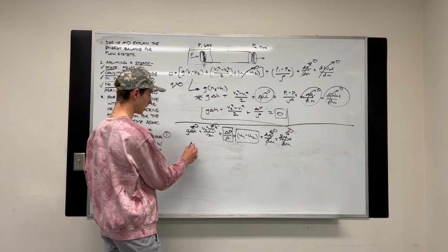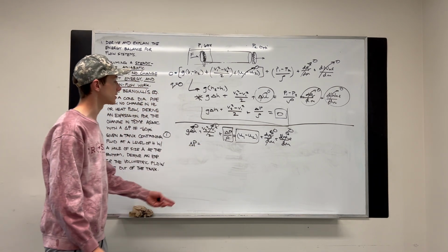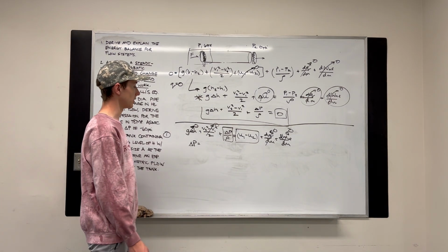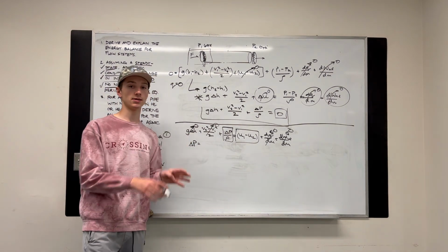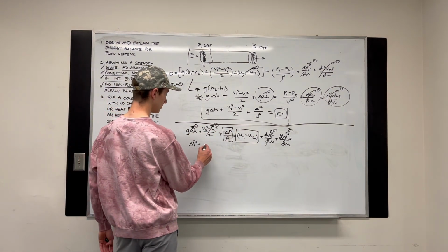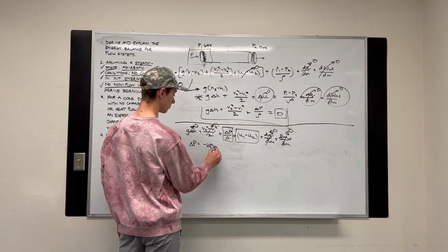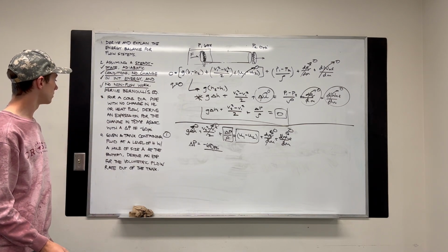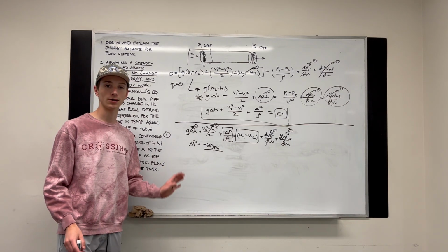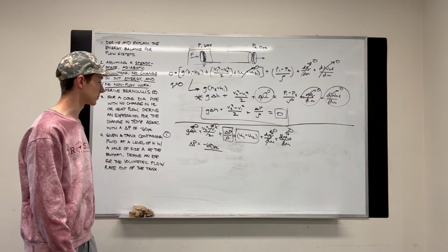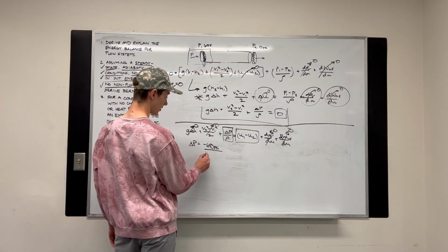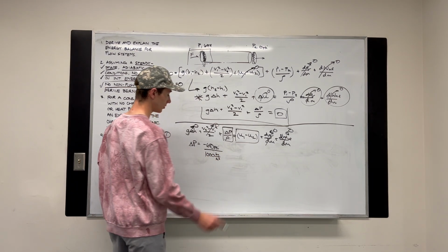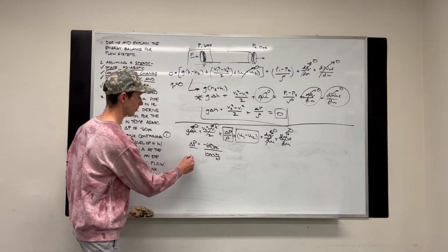So we said delta P, if we drop 60 psi, that is a delta P of, it'd be like 0 minus 60, right? P2 minus P1, so negative 60. Okay, and we're going to assume this is water. I don't think I wrote it down, but in this scenario, we're going to call this water. The density of water is 1,000 kilograms per meter cubed. We'll take care of our units here in a second. So that's delta P over rho.